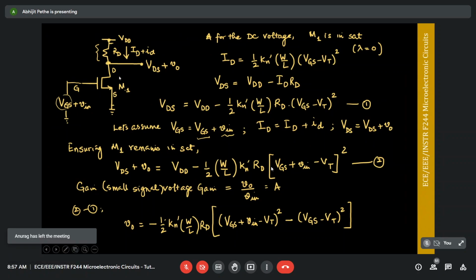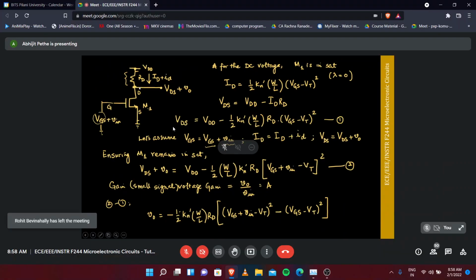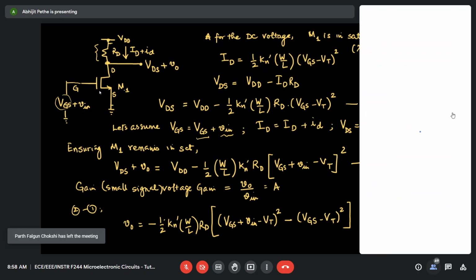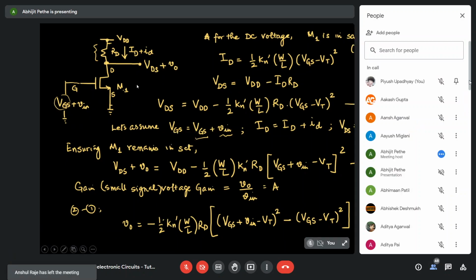When the MOSFET draws more current, more voltage falls across RD, right? Because the current flowing through the MOSFET is the current flowing through RD. So if you look at the voltage at node D, the voltage at node D actually is going to reduce if VGS increases. Is that clear? Sir, I'm asking why is there a 180-degree phase shift? No, the 180-degree phase shift, that's just the convention. What we're essentially seeing is that if I increase the gate voltage, my drain voltage is going down.